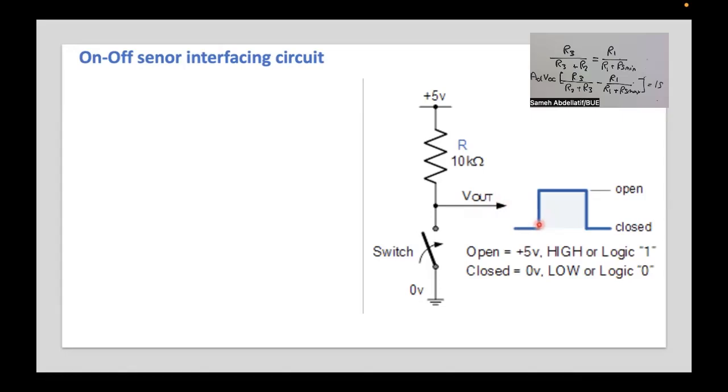Another important parameter here is the high frequency component. If you flash back to your signal classes, you will remember that high frequency components are usually embedded in the sharp edges. Whenever you have these ideal sharp edges, you should expect a high frequency component, which is usually a problem, knowing that any electronic system has a finite bandwidth. So when you have these very high frequency components, they will be clipped somehow when you go to next stages in your circuit. In order to get rid of that, which we call the bunching effect,